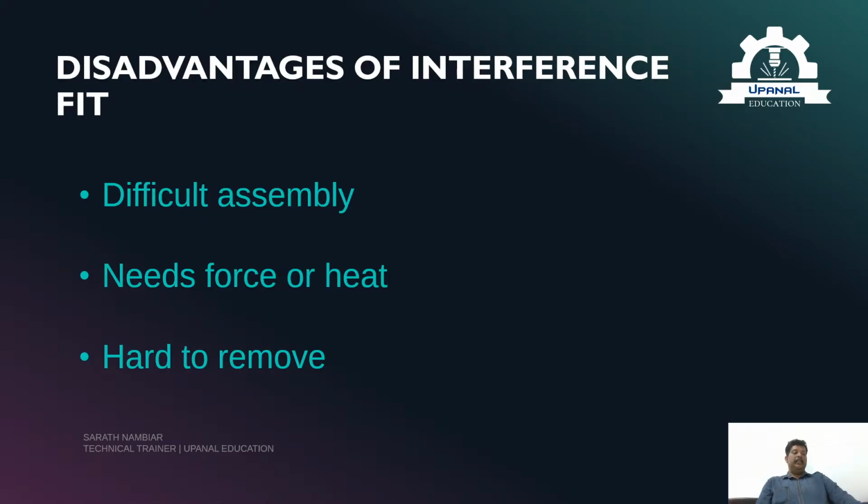Now, let's see the disadvantages. Since the shaft is bigger than the hole, obviously you can't assemble it by hand. It will not slide in easily. You will need either a press machine or heating methods. This will increase the assembly time, the equipment cost, and the skill requirement, and it will be difficult to remove. If the part needs to be replaced, it cannot be removed easily. Sometimes the parts get damaged during removal. So interference fit is very strong, but it is not very convenient for maintenance. That is why engineers use it only where absolutely necessary.